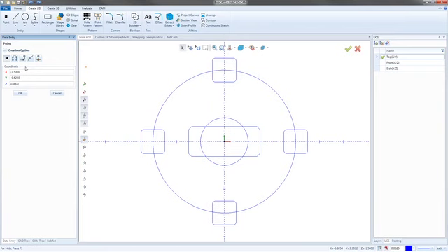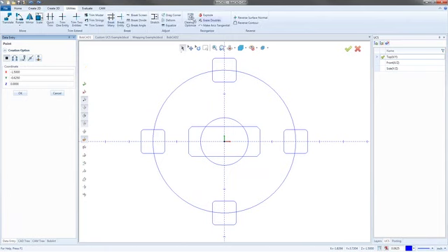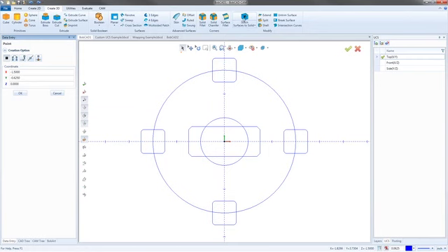What is the easiest way to create surfaces on the entire box, or do you have to planar each surface? Can you select an entire wireframe box? John, if you were to create a box out of 2D wireframe that was irregular and each side was just irregular, you'd have to skin each side together and then stitch it using the utilities. No, it's under Create 3D now. Using the stitch surfaces to solid function. So you create the walls of the box. So any box, doesn't really matter. And then you would stitch it together to make it one. Hope that answered that. If you got more, let me know. I'll get more into that with you if you want later on.